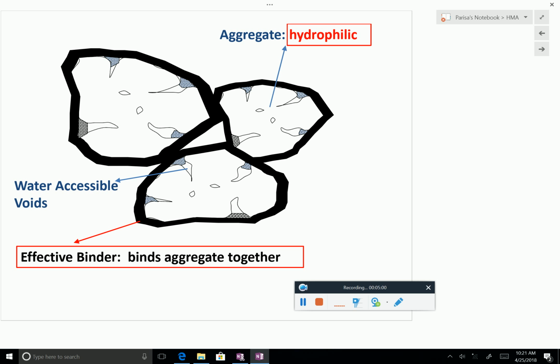Now, if you have water and the aggregates are such that they want to absorb water, they are hydrophilic, then they are going to absorb water. And you even know that if you want to glue two surfaces and one is wet, what happens? The glue peels off. You cannot really do that. You have to dry and clean, right? Exactly like here.